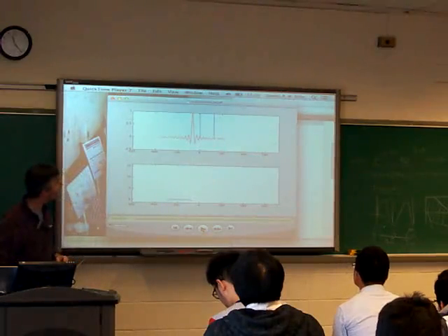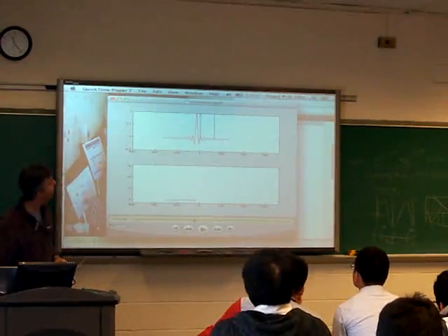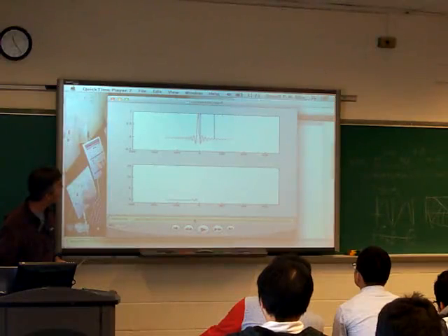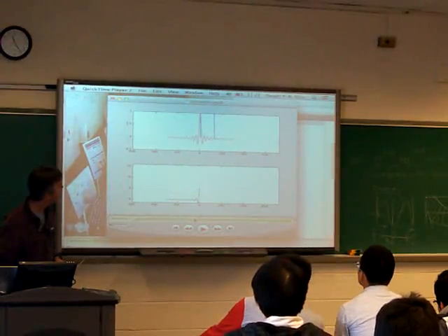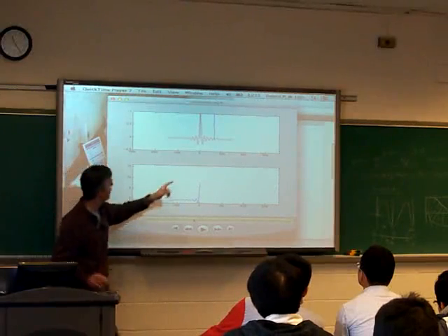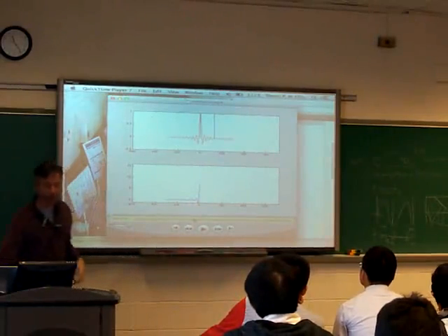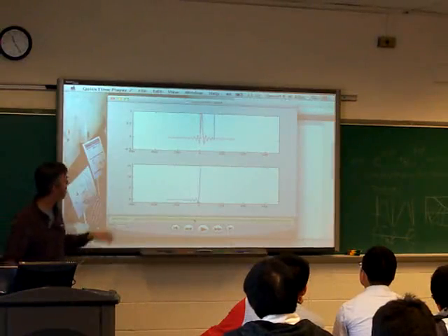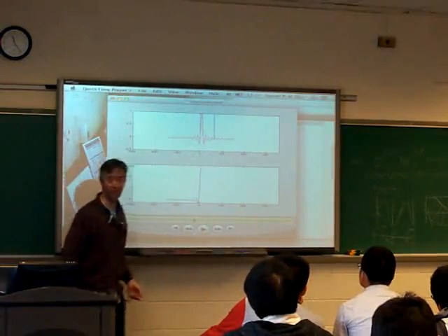When it gets interesting is when this large main lobe of the sinc function starts falling into the blue portion, and that's when we get our transition to the pass band, right? So now we've got half of this big main lobe in here, so we're halfway up, and we keep sliding in, and once we've got all of the main lobe in here, suddenly our magnitude response has gone up to be something large, because now we're including this big chunk in there.